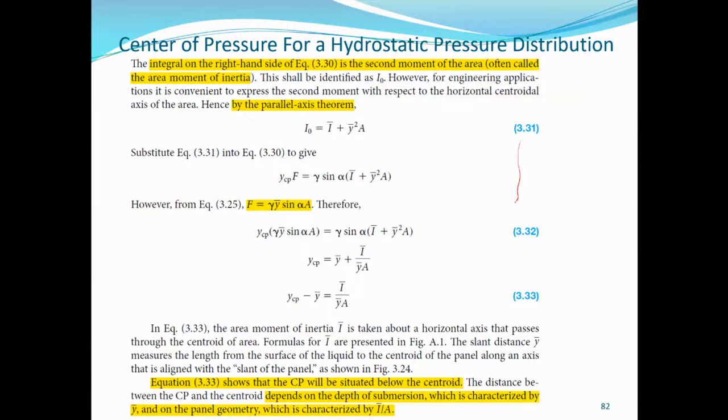Okay, if you have, let's say this is xy, and you have this rectangular body, you can determine its moment of inertia about the x-axis, which for a rectangle is bd cubed over 12. Now if it is not on the centroidal axis, you see here the x-axis through the centroid of the rectangular body. What if the rectangular body is at a distance?